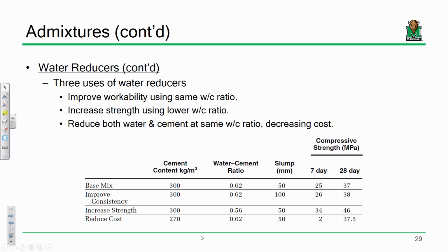And they can also increase the strength. The only thing that can be a little iffy is they do allow the concrete mix to remain workable, but once they wear off, the concrete will set, and it will set quick. So if you're going to use it, that's fine. You just got to be aware of that.